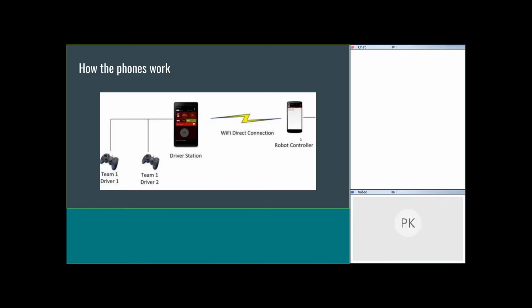for debugging before. For example, my FTC team couldn't understand why the robot wouldn't stop driving, and they didn't check specific things from the robot controller. The moment they checked it, they understood that the motors were spinning the wrong way and that the encoders weren't working because of that. So it's a very useful thing not only to send information but also to get information from the robot.